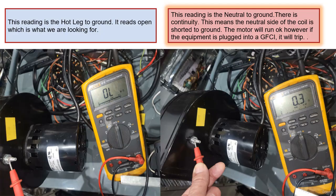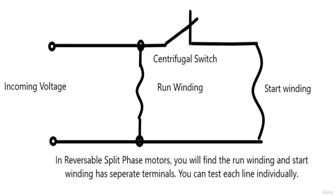You want to check to ground or the frame to ensure you have infinite ohms to ground. If you read any continuity to ground from a winding terminal, your coil is shorted. If you have split phases, which is a specific motor type, check each winding to ensure the windings aren't shorted to each other. Next is the running test.